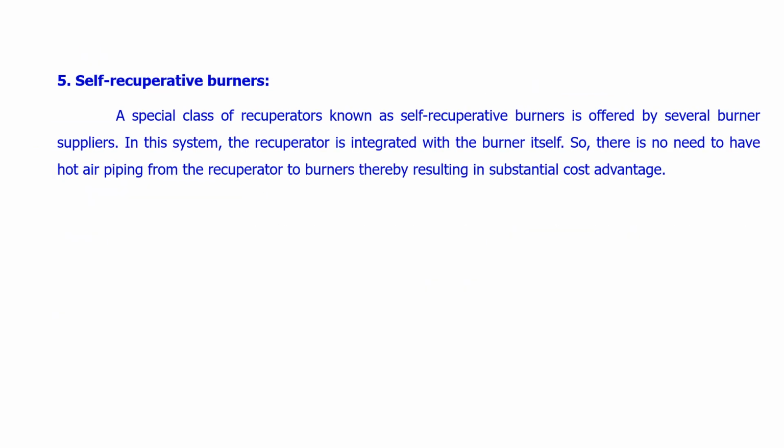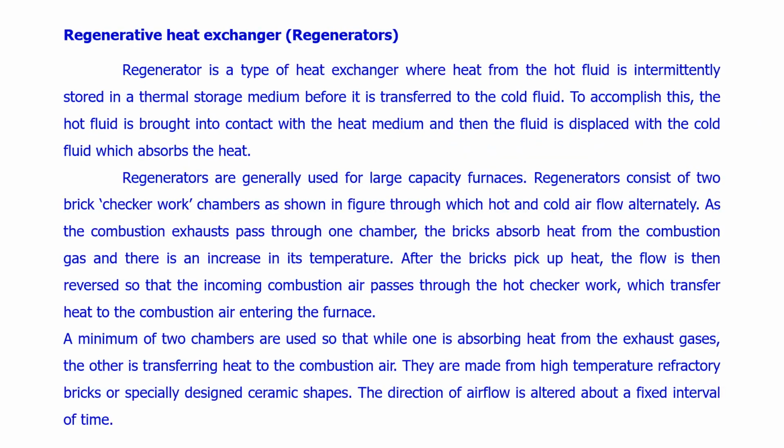Self-recuperative burners. This is a special type of recuperator in the form of a burner. The recuperator is integrated with the burner itself, so there is no need to have hot air piping from the recuperator to the burners. That's why it is called a self-recuperative burner. It is a cost advantage. The cost of the self-recuperative burner is comparatively lower than other types of recuperators.